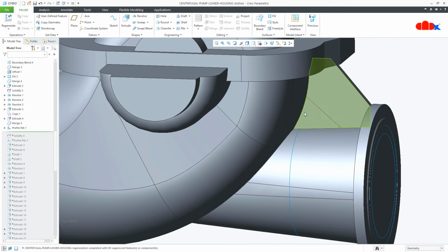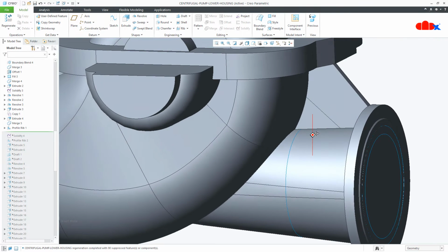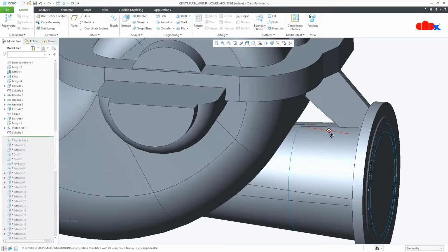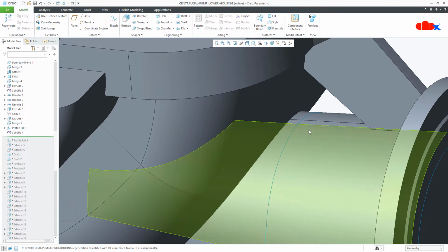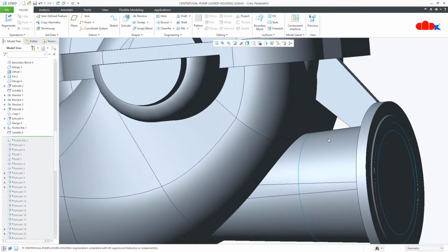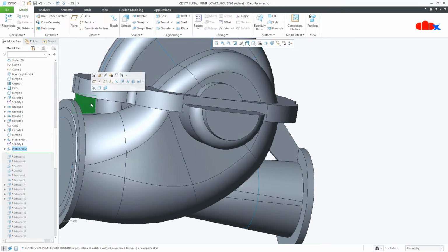Now to cut this portion, this surface is having different curvature, this is having different curvature. So it is not easy to remove the material by extrude cut, and for that we use surface and solidify to remove the material. So I get the same curvature here and here when I use the surface. Then one more rib, which is this side, this one.